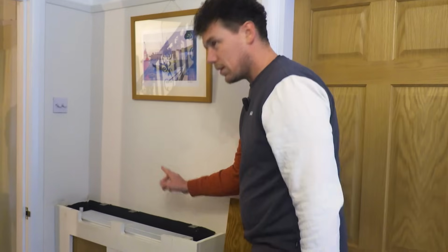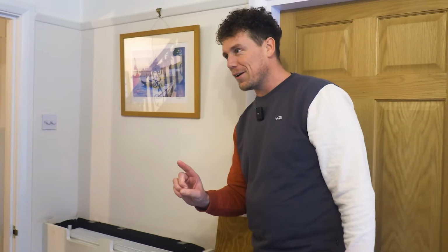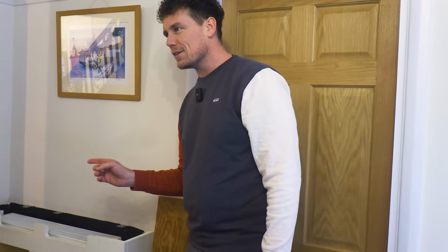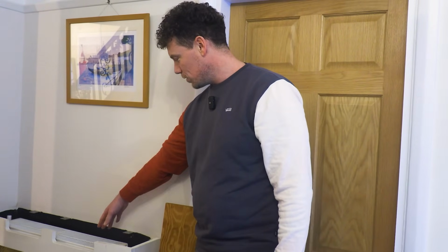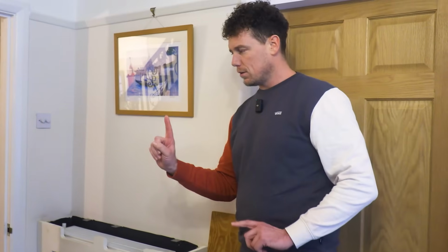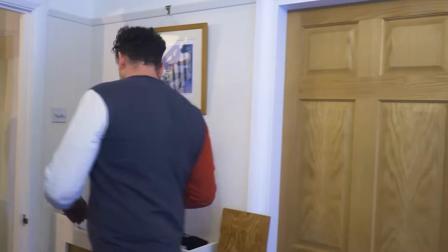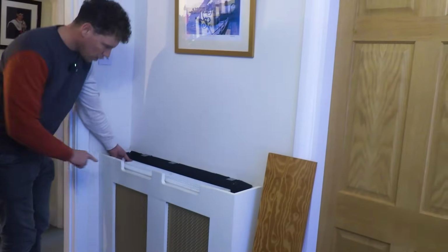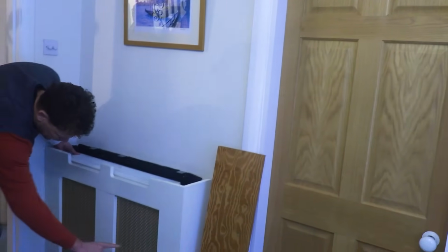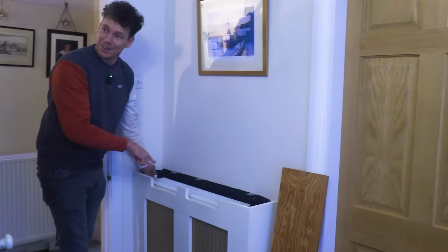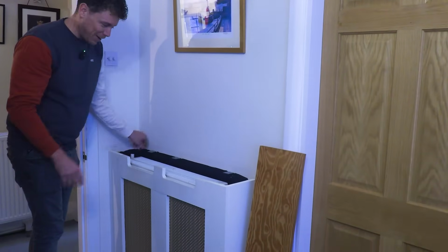The other thing, which is the opposite of that and undoes what I've just said, is that this is piped top, bottom, opposite ends, which is the old-fashioned way that we used to install radiators, rather than bottom and bottom, which allows heat to go up and then back down and leaves a little bit of a cold patch of lack of circulation. This is piped to the top here, which fills up the top of the radiator, and then it's taken out the bottom, and that actually adds the 5% back in. So it might work out.